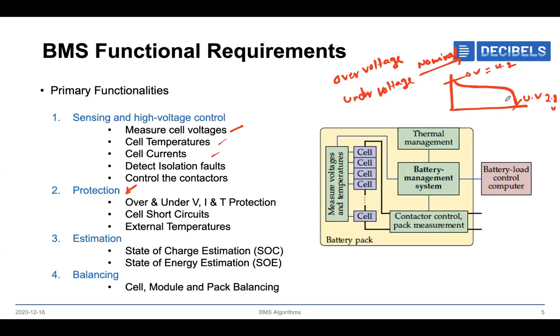And next one is controlling the current that you are discharging and charging. So if you look into the data sheets again, there will be C rates, which define how much current you can discharge from the cell. So let's say your cell capacity is 10 amp hour, then they'll mention continuous C rates as well as peak C rates. So if they say continuous is 10C and peak is 15C, and for this peak they'll mention the time also, which is like 5 milliseconds or 10 milliseconds, which means 15 times of 1C, so it will be 150 amps. We can discharge only for 5 milliseconds.